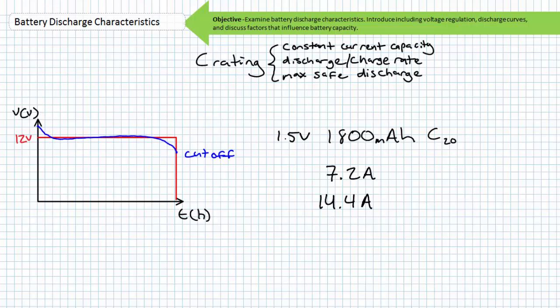Again, with your understanding of the inverse relationship of battery demand and supply, one can be reasonably certain that batteries, regardless of the magnitude of the safe discharge, will deplete themselves significantly faster and deliver significantly less energy than the nominal 1,800 milliamp hours when discharged at such high rates. In this case, the C rating is meant to be an expression of a battery's maximum safe discharge current.